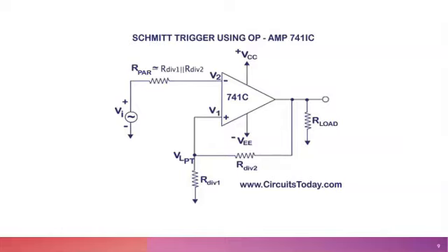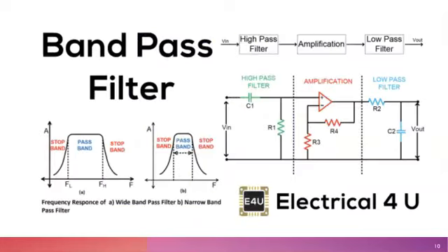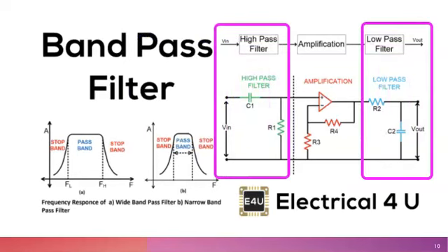In these applications, comparator ICs should be used rather than op-amps because they are designed to operate in this mode. In other op-amp circuits, the feedback may be used to provide other effects such as filtering and the like. One aspect closely associated with op-amp gain is the bandwidth.